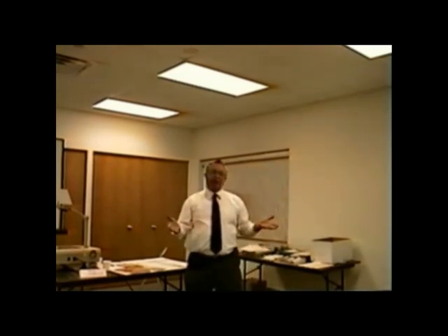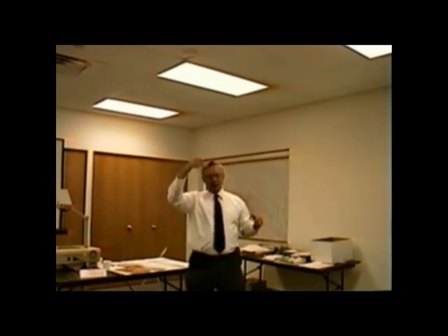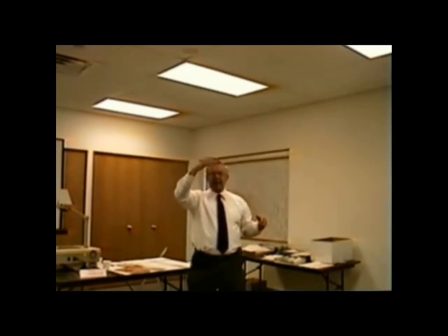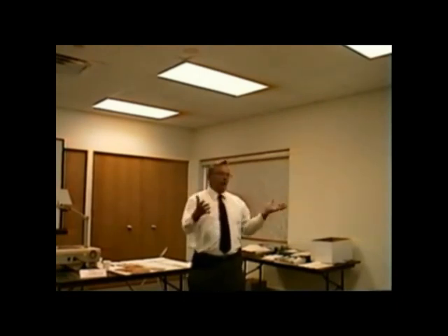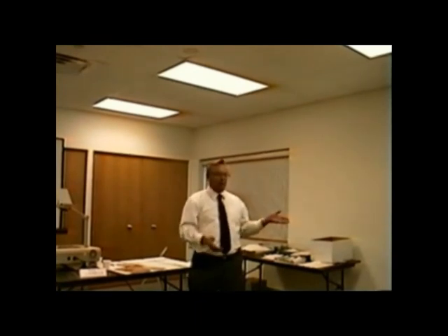put a piece of cardboard where the filter is, or we pull the blower wire, and we let the heat exchanger sit there and bake, and as soon as the high main limit gets hot enough, it's going to open up and the fire goes off. And that's the way you sell yourself and your company. If you ever want to show that to your customer, it works out terrific.